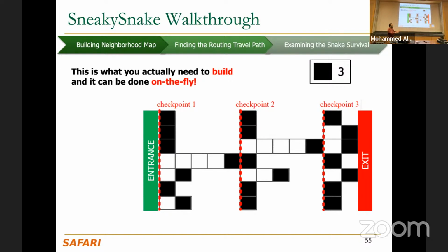You don't need to do that, but we don't do that for a simple reason: we are doing FPGA. In FPGA, you need to hard code everything. You cannot do special cases for certain paths. Otherwise, you cannot replicate the instances doing the same job. So, for example, each instance can calculate 16 steps forward, and then you replicate it as many times as you have rows, and that will give you everything in parallel, in one shot. That's one of the reasons.